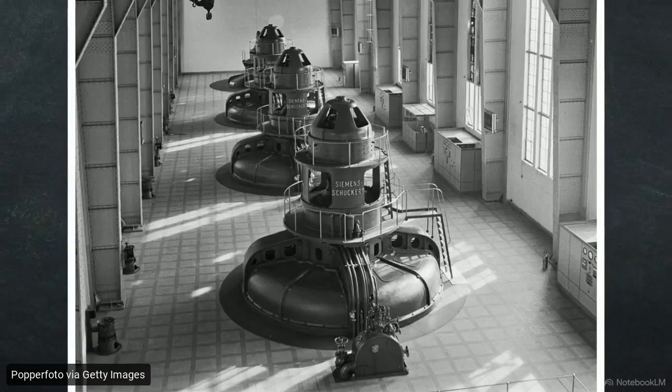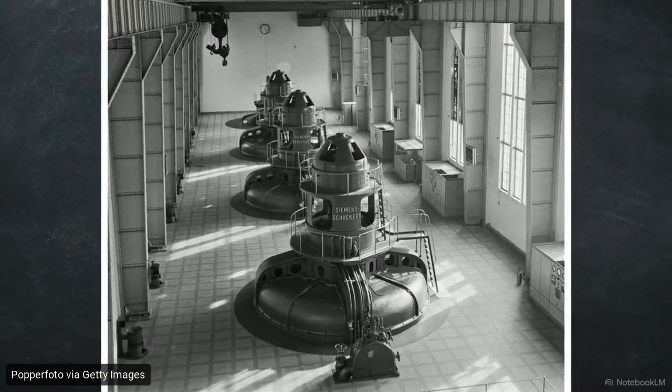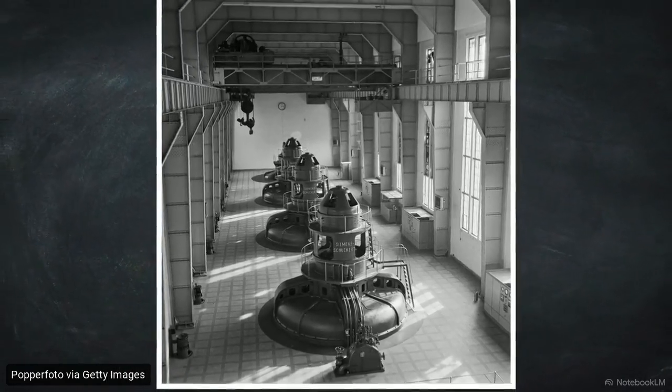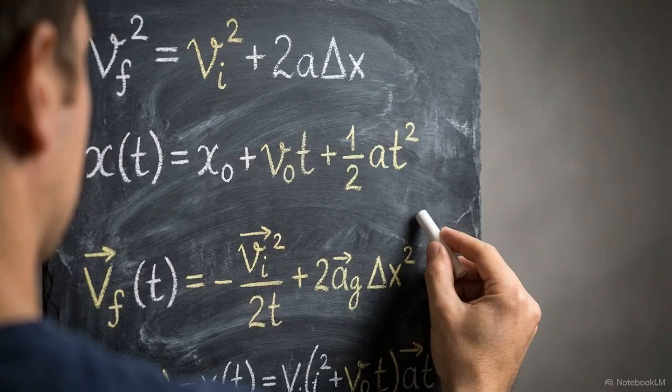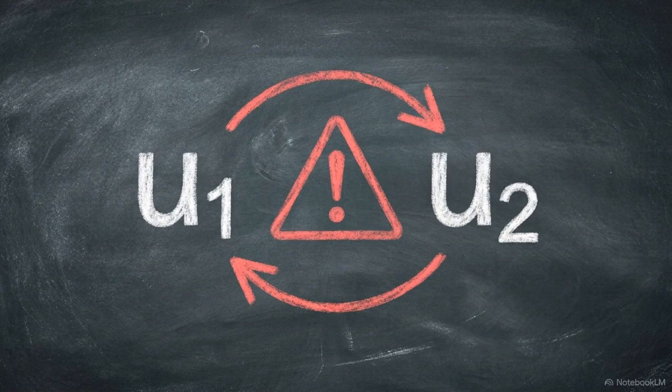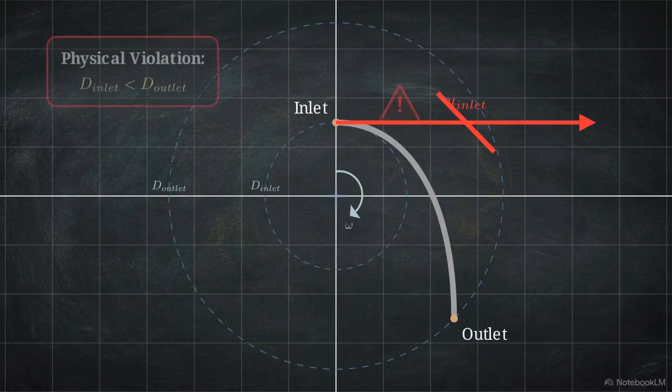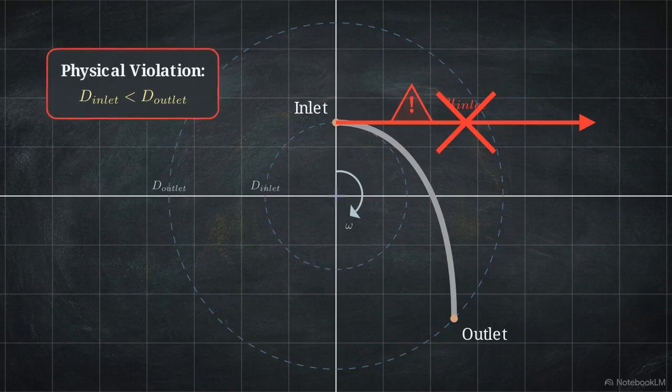These geometric constructions function as direct, calculable predictors of a hydroelectric plant's exact megawatt output. So how do we apply this theoretical model to actual numerical problem solving? The single most common error in kinematic analysis is misassigning the inner and outer peripheral blade velocities. If you treat this like a standard inward flow Francis turbine, you will plug the larger velocity into the inlet side of the equation. In an outward flow model, doing that violates the machine's physical boundary conditions.